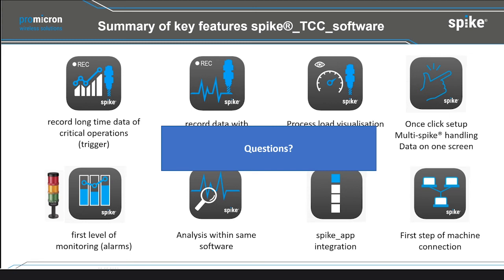In the next step, we will have the option of streaming or connecting our data with foreign systems, and even connecting it to the tool management system, or we are even running projects with universities and so on to link our force data with the position of the axis, so the position of the tool on the workpiece.